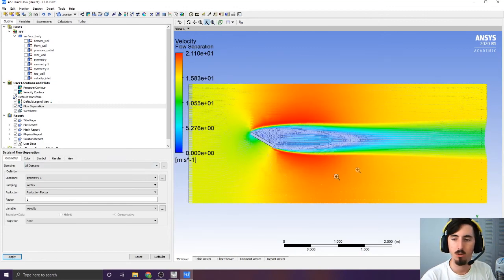All right. So hope that was helpful for you guys. If you have multiple cases, you want to show a flat plate, you want to show a 90-degree plate, you can make airfoils, you can chamfer these edges, you can change some of the geometry to this and make it more aerodynamic and get an idea of where that is. Obviously, a teardrop shape would be the best way to kind of see this and see not necessarily flow separation, but how different shapes could mitigate that flow separation.